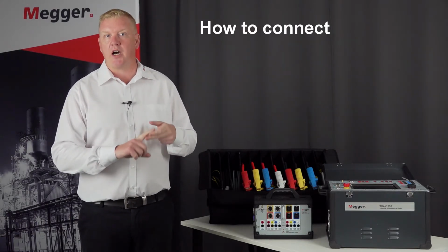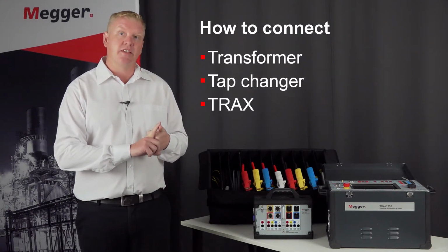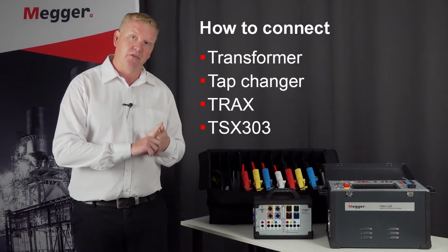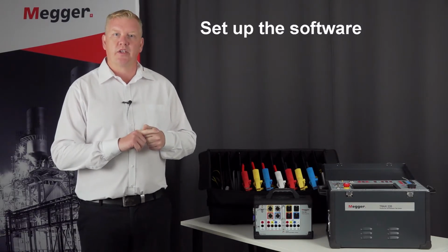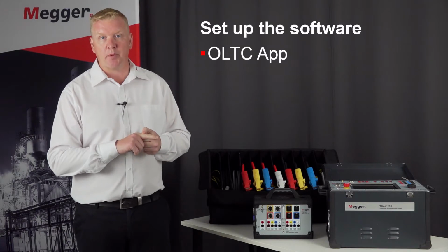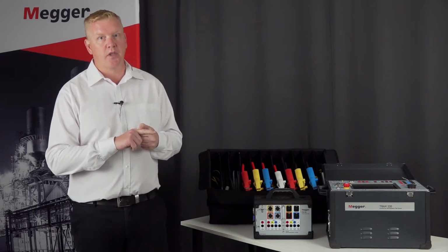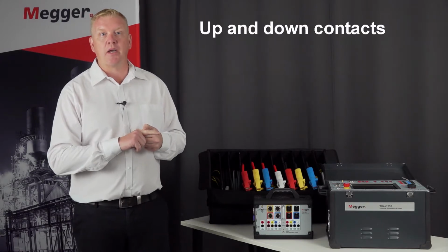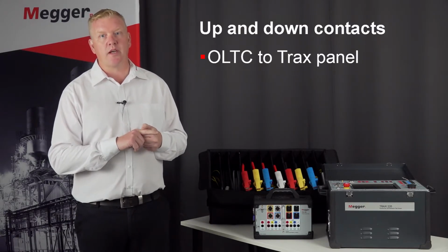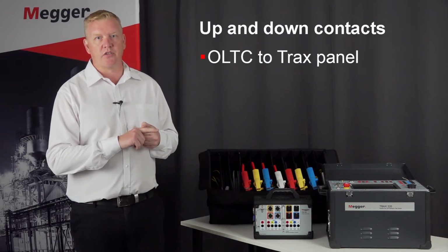Here we will cover how to connect to your transformer and the tap changer with the TRAX and the TSX303, the automatic switch box. How to set up the software and use the dedicated on-load tap changer app, connect the motor current clamp and set up the software for that, as well as connect the up and down contacts from the on-load tap changer to the TRAX panel for full automatic functionality of your testing. Please enjoy!